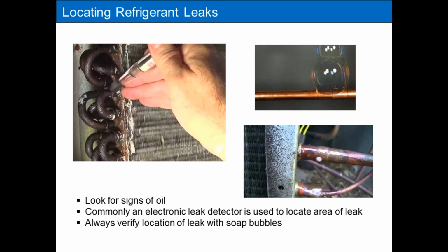If you have a leak in an evaporator coil, best practice is to change the coil out. You can try fixing the coils, but you might be chasing your tail. Sometimes you'll fix one leak and then another leak develops. You'll fix another leak and another leak develops. Sometimes it's best just to cut your losses and change out the entire evaporator if you find the leak is in the evaporator. It's not always in the evaporator, but it's pretty common in a lot of these cases.